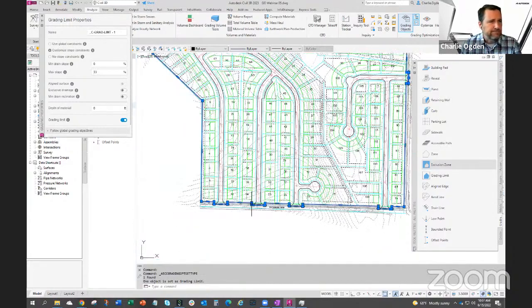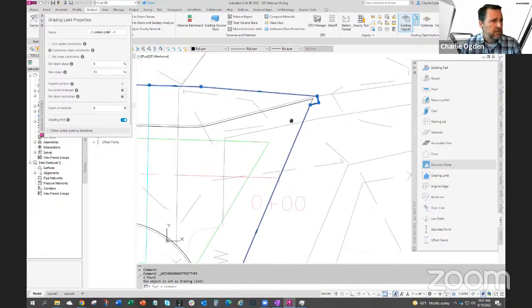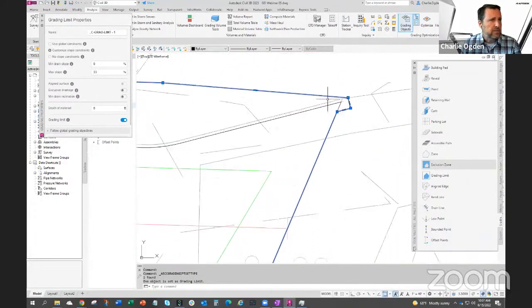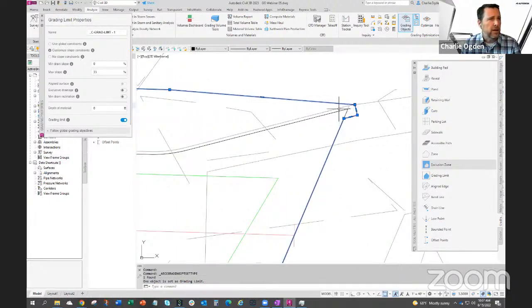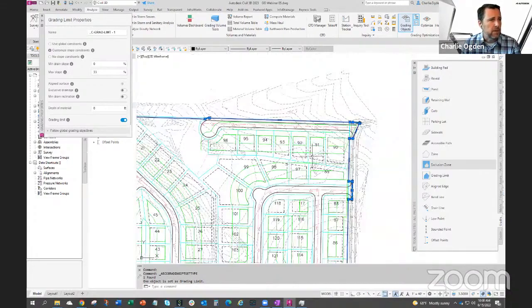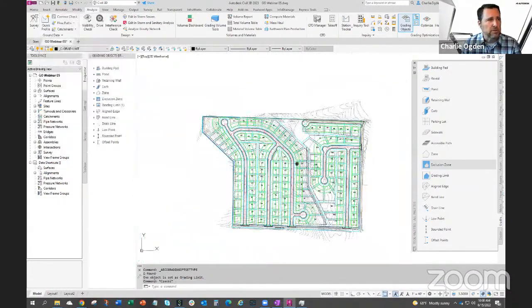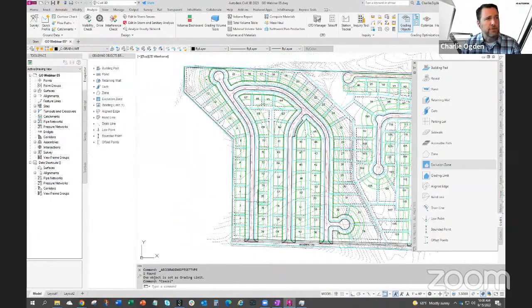And also in some cases, maybe take some caution. I have curbs here. Curbs are going to be offset back about half a foot, which I think is roughly where this gray line is. So I also want the whole curb, even though my line work is the front. I wanted the offset to the back of the curb to also be within my grading limit. Otherwise, your curbs might get ignored. So if you notice that happening, first check and make sure they're inside your grading limit.